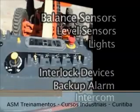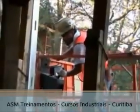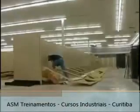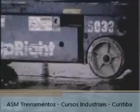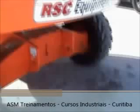The emergency descent system should be checked by raising the platform a couple of feet and then turning the lift off and using the auxiliary power to lower the lift. It is necessary to always inspect the work site prior to using the lift. The ground on which the lift will be used needs to be solid and as level as possible. Do not use a lift on unstable ground.